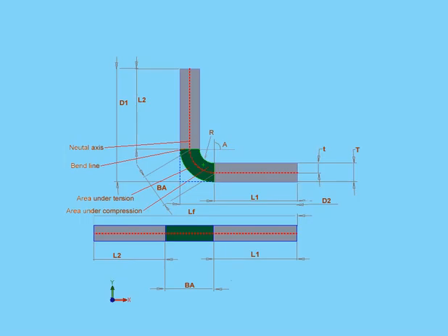Before we get rolling, I wanted to comment on something. There's not really a scientific method or formula for determining a truly exact calculation of the bend allowance, and that's because there's so many factors at play during the production of your sheet metal part. For example, actual material thickness, an infinite variety of tooling conditions, forming methods, on and on and on. There are many variables here, and in reality, many methods are used to calculate bend allowance. Trial and error is probably the most popular one.